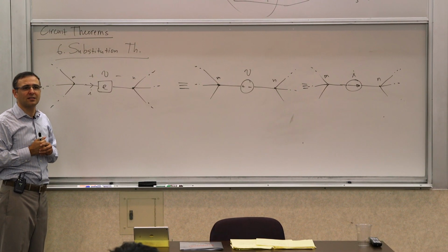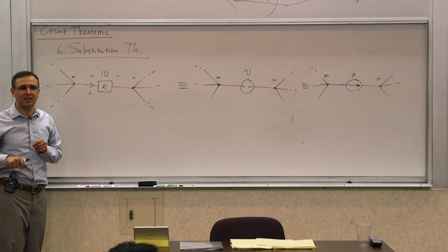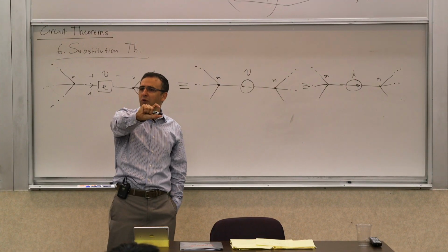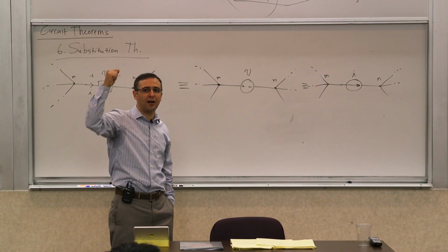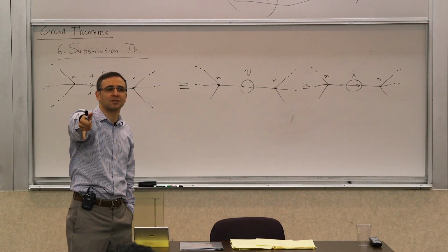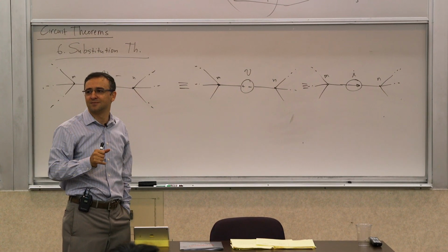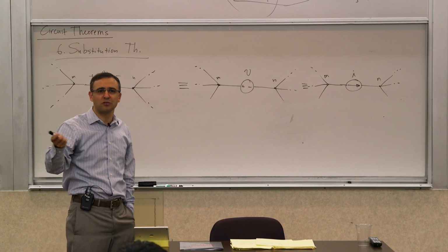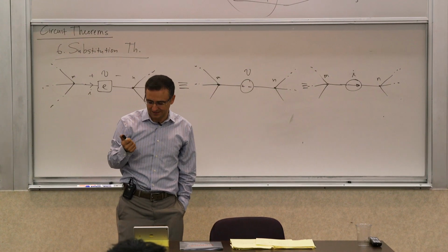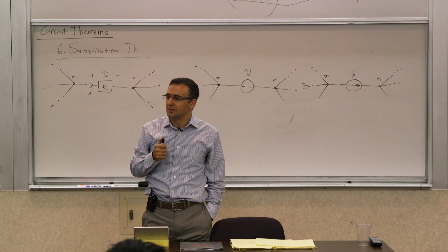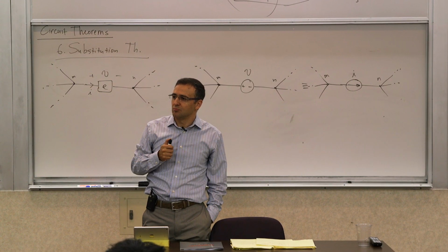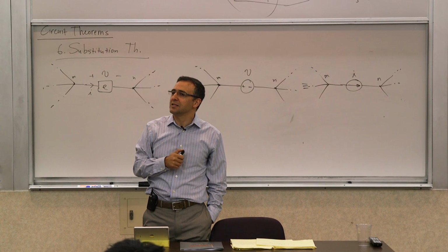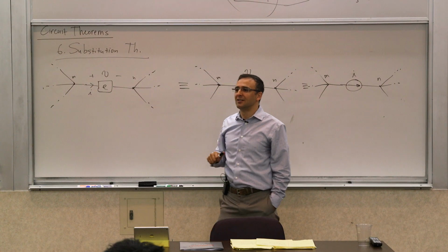This is actually interesting, isn't it? So if you have a resistor in a network, in a big circuit, and you look at it and say, its voltage is 2 volts, I can take it out, replace it with a voltage source of 2 volts, and nothing else in that network will change. What about its impedance? Sure, it changes the impedance that's seen, but it doesn't change anything else in the network. It says that nobody else will notice the change.